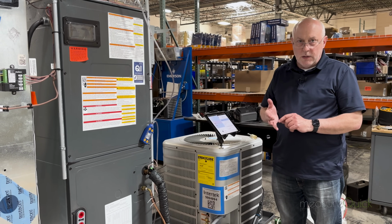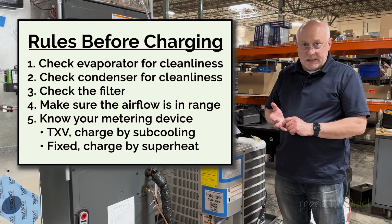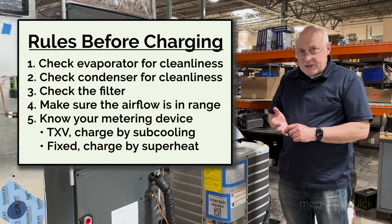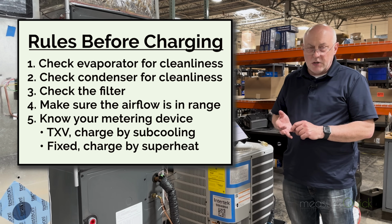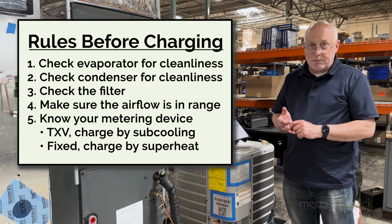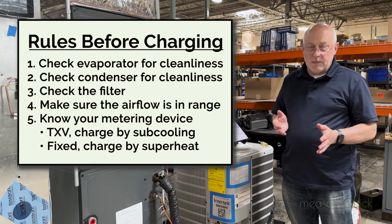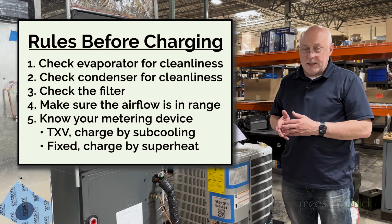We make sure that we check the filter, make sure it's clean, check the evaporator coil, it's clean, check the blower, make sure it's clean, check the condenser coil, make sure it's clean. Make sure everything's clean before we adjust charge. Check our airflow, at minimum by static pressure, just by getting a quick static pressure reading to make sure we're in the right range. And then we can start to charge the system. And again, we identify the metering device to make sure that we are charging by either superheat or subcooling.